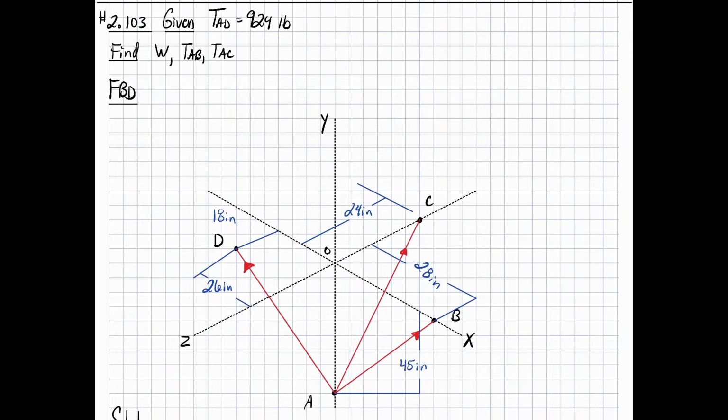Looks like I do have a question here. Is the resultant formula always R is equal to Ry over the sine of that alpha? Or will it sometimes be R is equal to Ry over cosine alpha? So what I did for that instance is I used the law of sines. So that's I used Ry and sine. If I was to use the cosine, I'd have to use the Rx over cosine alpha. So whichever one you use, if you use cosine, you use Rx. If you use sine, it's going to be Ry. Hopefully that kind of clears that up.